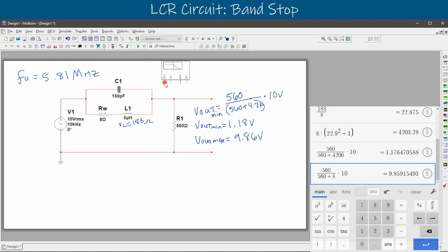And this one compares the front end of the circuit, the voltage, to the back end, the voltage out. And so we can place our input around the input voltage by grabbing our positive in line and going to the front half of our circuit here, right in front of our voltage line. The negative one goes to our negative side or ground, which is anywhere on this bottom wire all the way across. The second half, our output, is going to go around our output resistor, and that is where we pull off of this circuit to go to another circuit if we wanted to filter the incoming and pull out the output. So we're going to put the output at the top of our resistor right here. That's anywhere on this line. And the negative side of this output goes to the ground line or the bottom side of the resistor. So the same spot that the other one was.